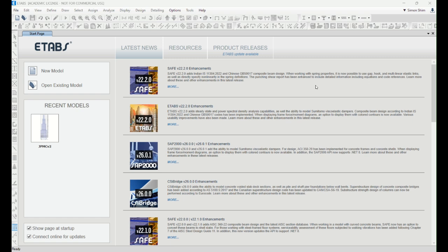If we have some time, I'm going to duplicate all the floors up to 40 stories and run it, and we're going to do the column load takedown. So all the floor loading should be accumulated, and then we should be able to calculate all the actual load for the columns. If we have a little bit more time, I'm going to run the steel column design as well. So let's get started.